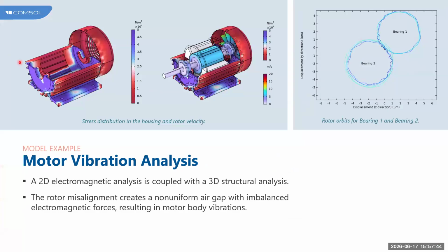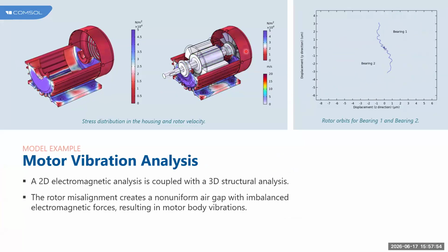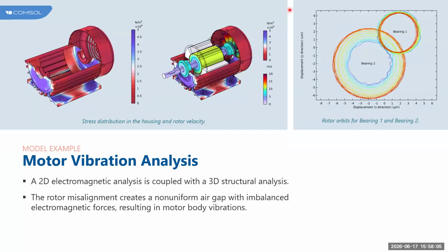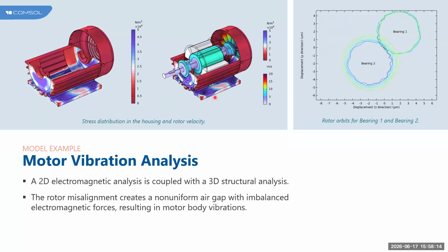When we evaluate the stresses in, say, the external casing of this particular motor, for acoustic analysis or to evaluate the radiated noise, you just need the structural acceleration at the boundaries of the casing. We will include an air domain outside the outer casing, and you would use that structural acceleration as the source to assess the acoustic sound.